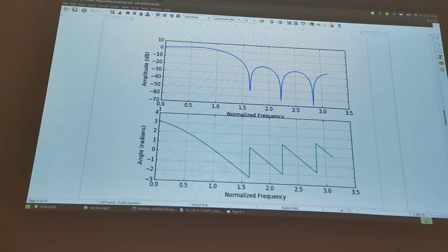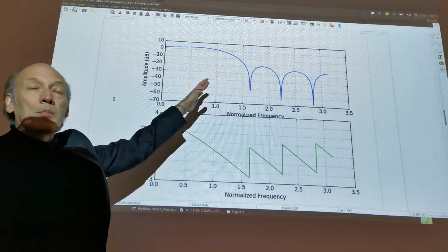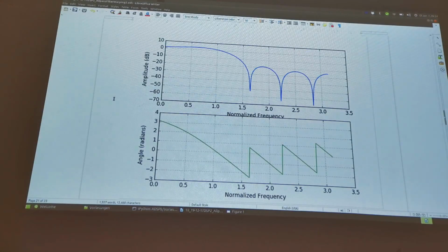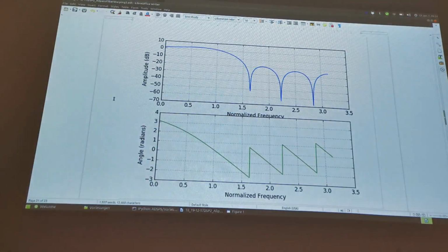For instance, if you have somebody on the telephone or using teleconferencing, you don't want the speech to be delayed too much by the filtering on the way. So here you have such a version. You have a good magnitude response, so this still works nicely as a low-pass filter, the same low-pass filter as before, but it has much less delay than the linear phase version. And the slight non-linearity usually doesn't really matter. Right? The big advantage here is the low delay.